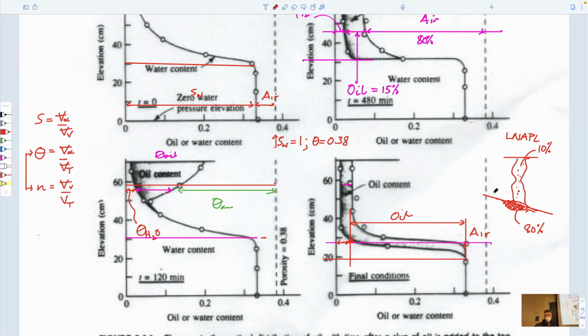And so the original water table would have had a tension saturated zone above it. This is what we'd call the capillary fringe. Or the tension saturated zone. This is the top of the capillary fringe. The capillary fringe would be the area. Fringe is an area. And that would be the top of it. And so it starts looking like the systems we looked at.